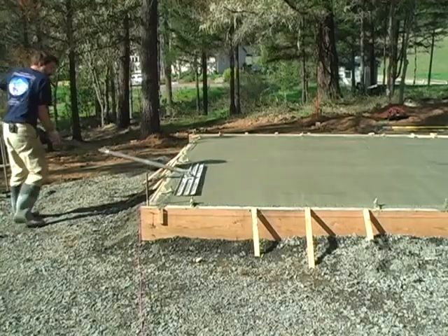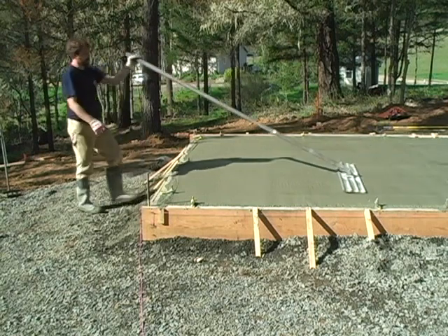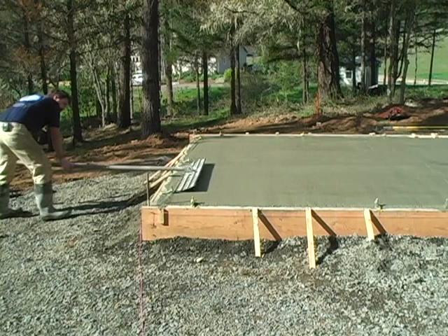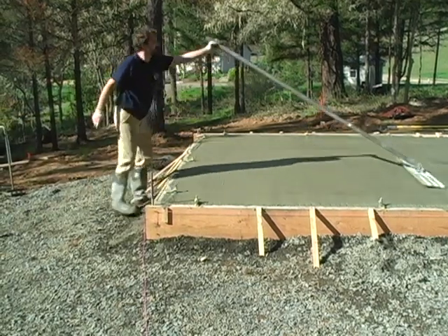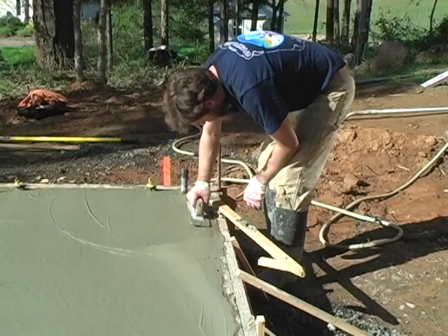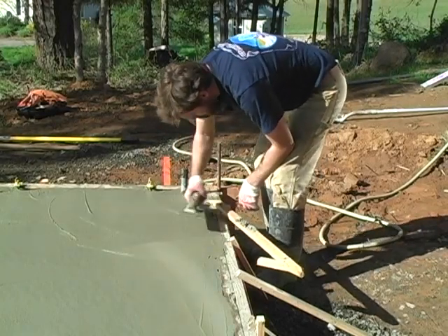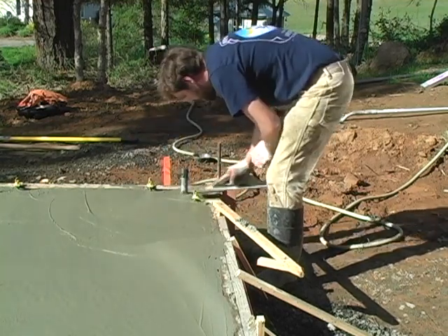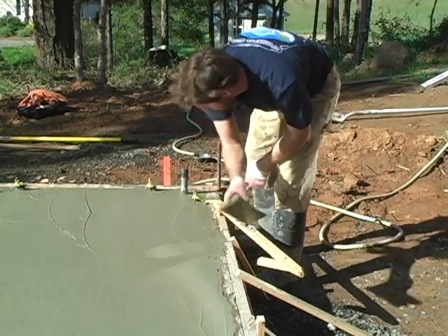So now I'm just continuing around the surface of the slab and working the cream a little bit. I want to be careful not to overwork it, but at the same time, I want to be sure my level is as smooth as I can make it. So here around the edges, I'm using my magnesium float, and I'm coming off of the form boards as my screed to get my general elevation, and then I can just use it to clean up like this.